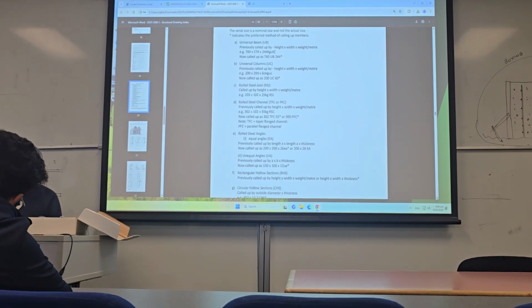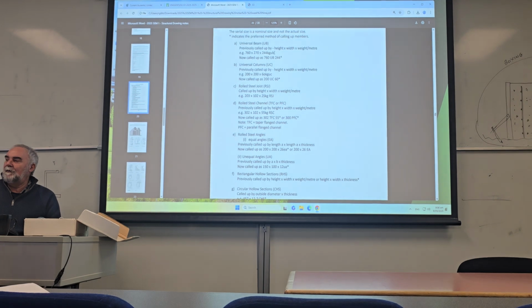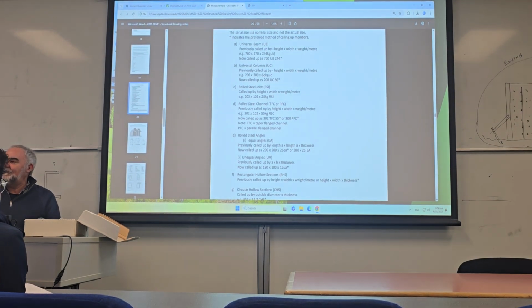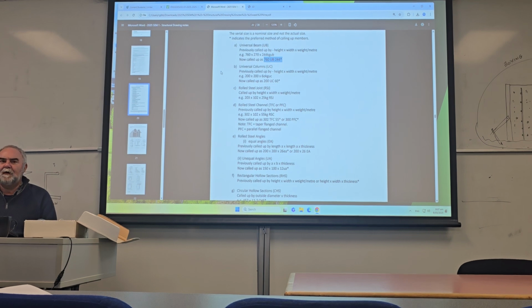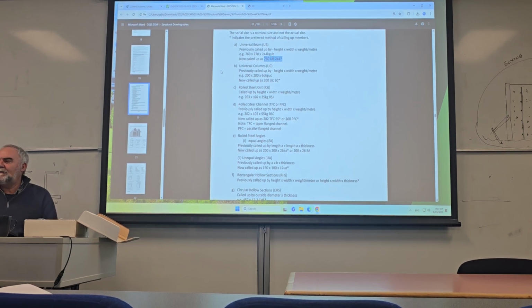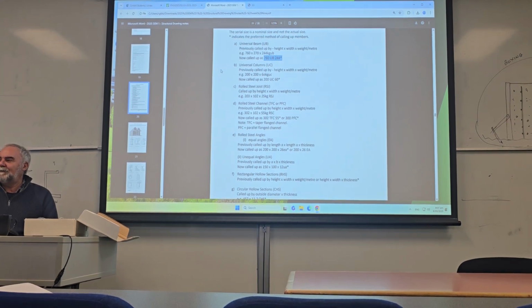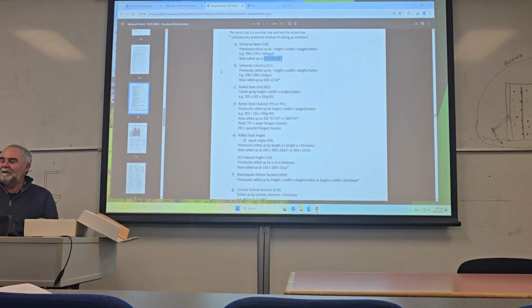Nowadays, in fact, probably since about the year 2000 or more, we call it up as a 760 UB 244. Why would I be doing that? Why don't I just say universal beam? Call it up as a 760 UB 244. Universal column, let's just call it up as 200 UC 60. Why have I bothered showing you how we used to do it back when the dinosaurs were on the planet?